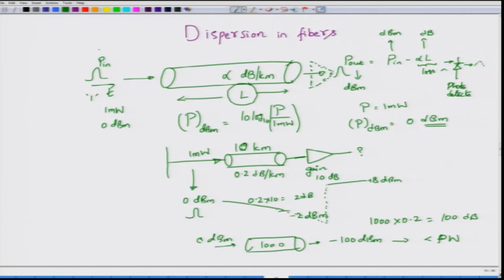So, the maximum distance of fiber before we need to place an optical amplifier for the system operation conditions is called a span. Okay. So, what this attenuation does to our optical pulses propagating in the fiber is to reduce the span length. Okay. So, that was attenuation. Just to summarize the first few minutes that we have talked about, attenuation limits the maximum span length.